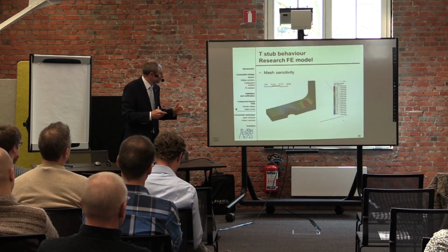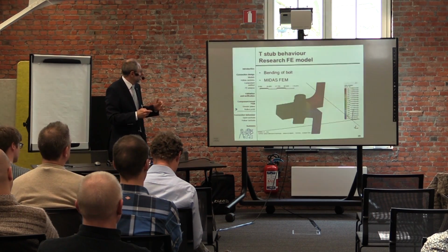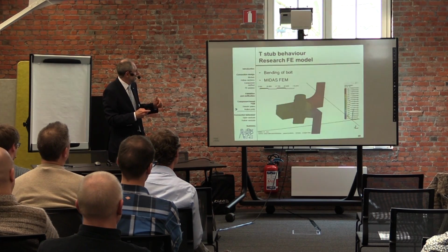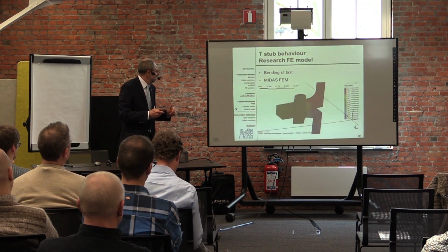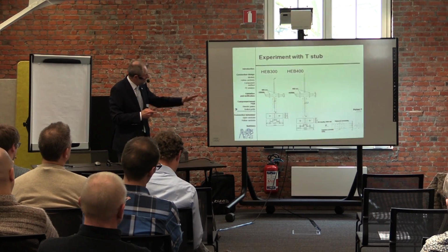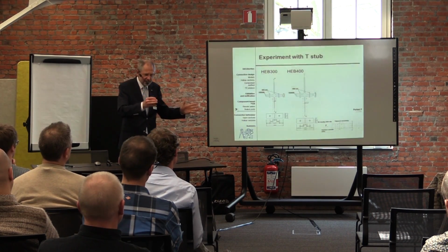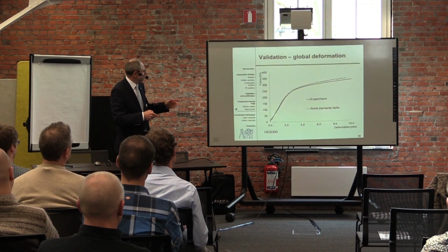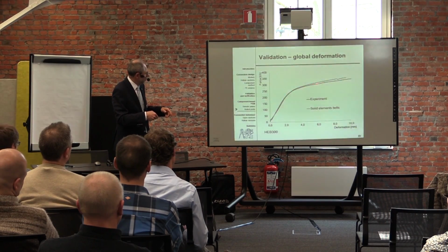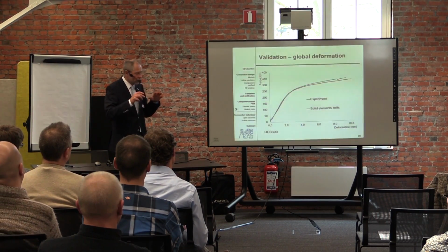Here it is prepared in Midas software and CBFEM. And we did also in literature, at the beginning of this, JASPAR experiments, but we did our own test once more. It's not so complicated, to have our own values to be able to validate it. So here you see our test, our instrumentation, and here you see validation of the solid bolt element against the test. It is global behavior.